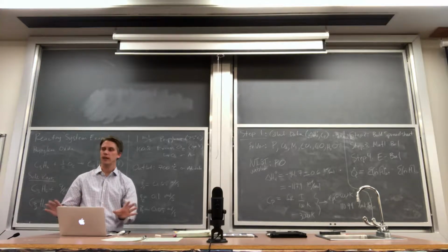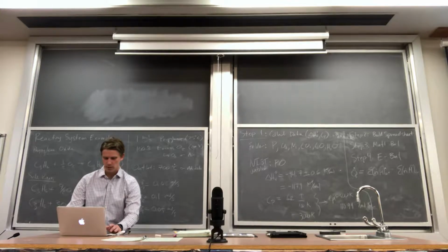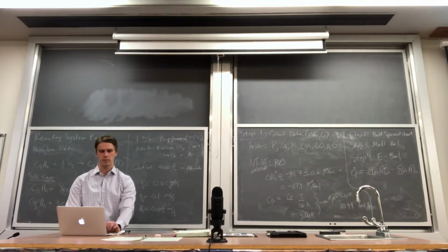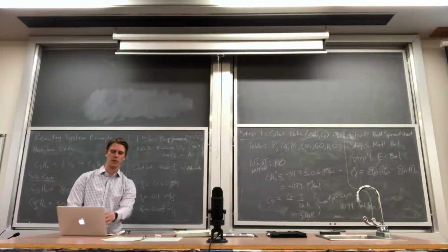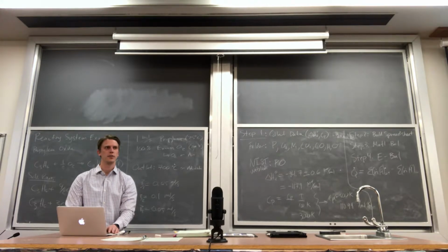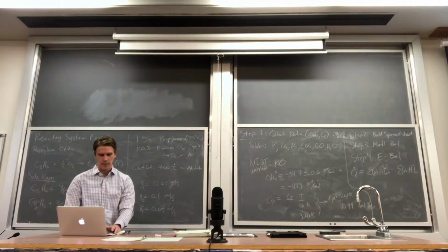So I can change anything I want. I could change this to 1,000 degrees C output, right? And everything automatically updates and solves just fine, right? This one here, I put 1 if it's air and 0 if it's oxygen. So if it's pure oxygen, you see that the nitrogen term goes to 0. If it's 1, it doesn't go to 0. So just little programming tricks like that to make it work well for a demonstration.